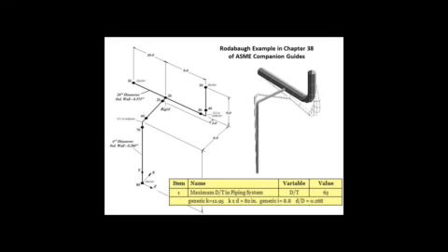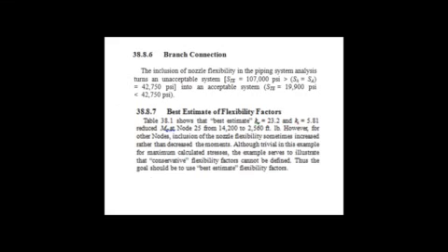The branch runs are 9 foot 9 inches. So we've got 82 inches over 117 inches, which is about 70%. So of the flexibility in the Y direction for the branch, the flexibility gives us a total of 70%. So we've got a significant contributor to the overall length of the system by the effective length of the flexibility of the branch.